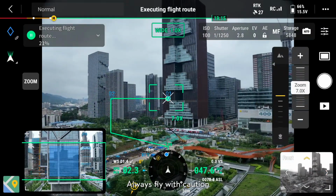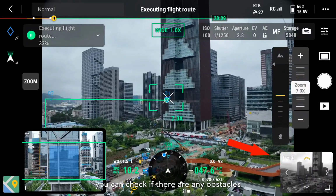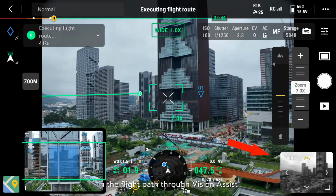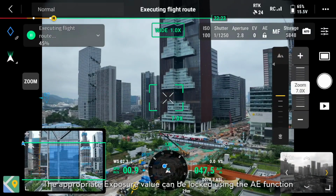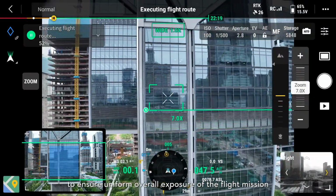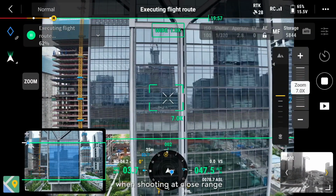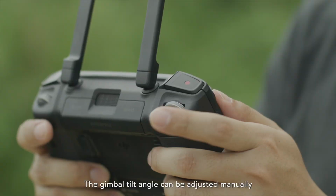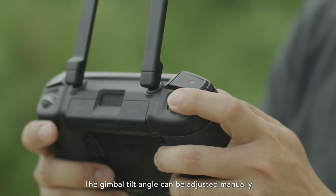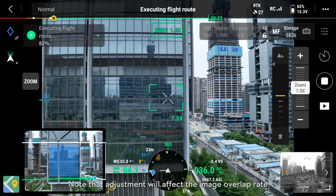Always fly with caution. When performing the flight route mission, you can check if there are any obstacles in the flight path through Vision Assist. The appropriate exposure value can be locked using the AE function to ensure uniform overall exposure of the flight mission. Please pay attention to the camera focus when shooting at close range. The gimbal tilt angle can be adjusted manually during the mission. Note that adjustment will affect the image overlap rate.